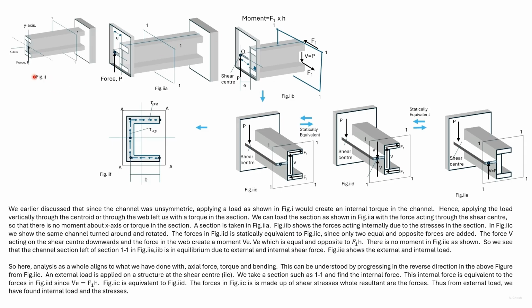We earlier discussed that if we have a vertical force applied as shown, either acting on the centroid or along the web of the channel section, then there will be a torque on the channel section apart from shear force. If we apply the vertical force at the shear center, then there will be no torque acting on the channel section.